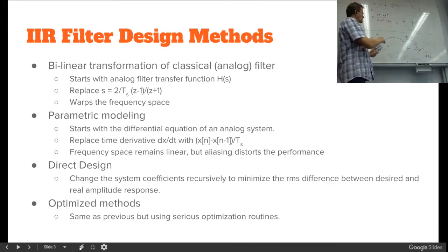And when you are on a z-plane, you can actually make sure that you do not accidentally move a pole outside of the unit circle. If you are tweaking these system coefficients directly, then you have the danger that you will move those outside of the unit circle, or easily lose some attenuation, because your zero position actually slips out of the unit circle.